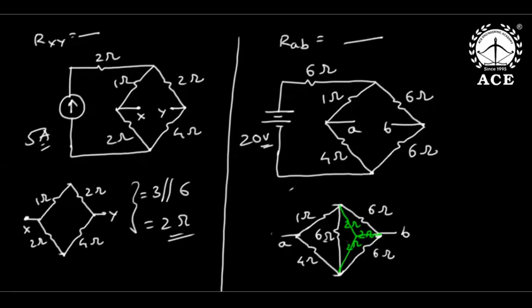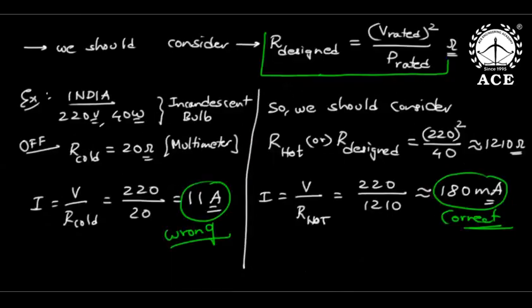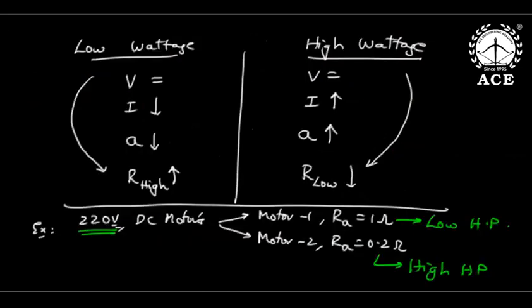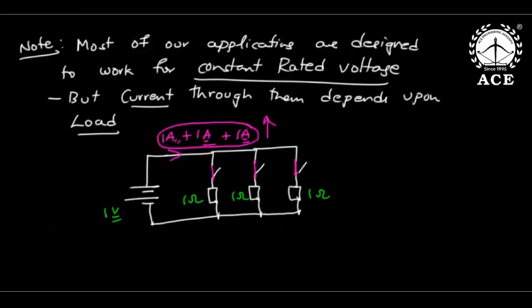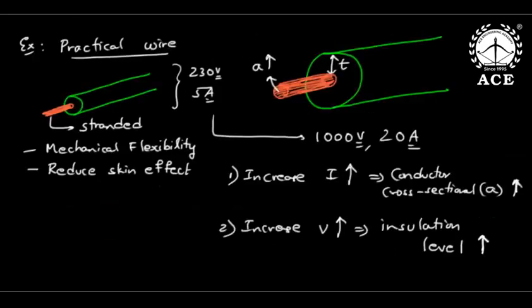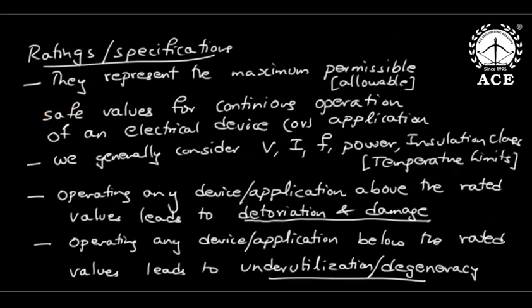Anil, tell me. Sir, can you please explain that again? KVL violations. See, if two voltage sources are in parallel of different values, that is wrong because you cannot write a KVL. Ideal voltage sources of different values cannot be connected in parallel. That is what I told.